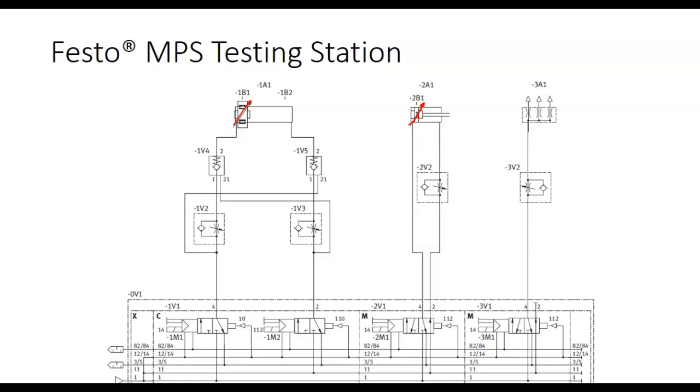Normally, what we do on these cylinders, especially big hydraulic cylinders that are moving pretty fast, is we put a cushion in them. It's not a real cushion. What it is, it's a little pilot valve that when it gets close to the end, it can't vent, and it's got to go through the little pilot hole. We call these variable cushions. They just keep the cylinder from slamming into the end caps. So that's what that means.